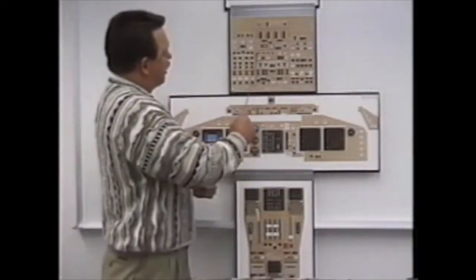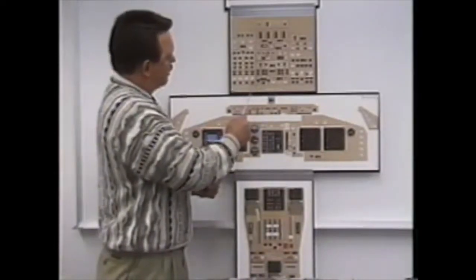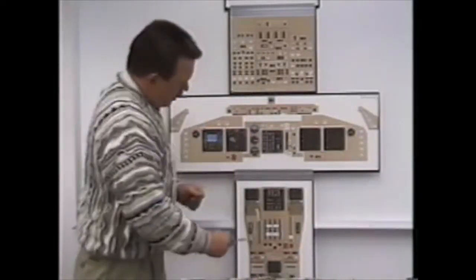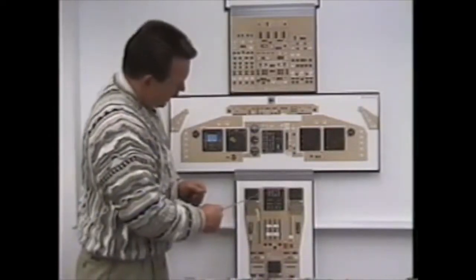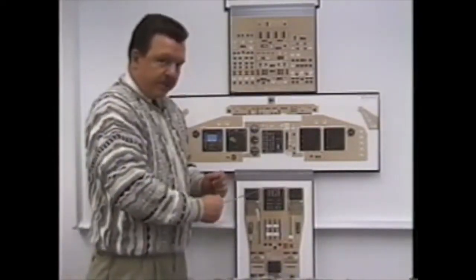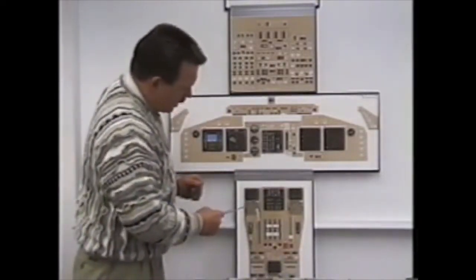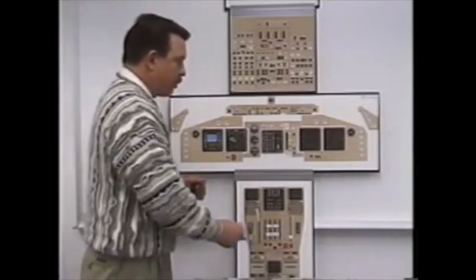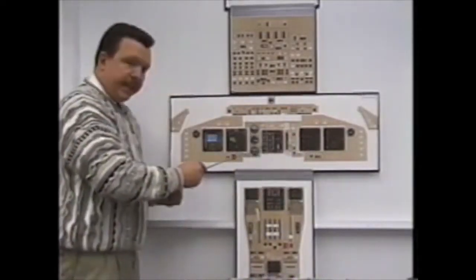Reviewing now the engine start sequence and abnormal start procedures. Using the start switches on the overhead panel, engine start sequence is engine 4, 1, 2, 3. Once the engine is starting, the first officer will bring the fuel lever up to run when the N2 indicates 25% or max motoring, whichever occurs first, provided we're motoring above the minimum fuel on line. First officer brings the fuel lever up to run and hacks the clock. We have 20 seconds to have a light off indicated.